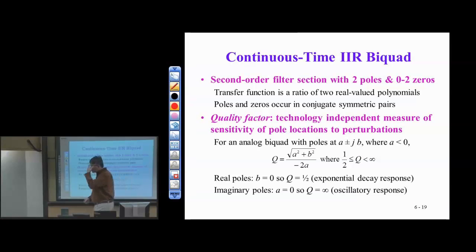All right, let's talk about biquads in a little more detail. Remember, biquads are a building block, and we can use them in parallel and also in cascaded combination to realize a higher order transfer function. And I'll have a bit to say about that in just a second. So you'll need this next week in lab.